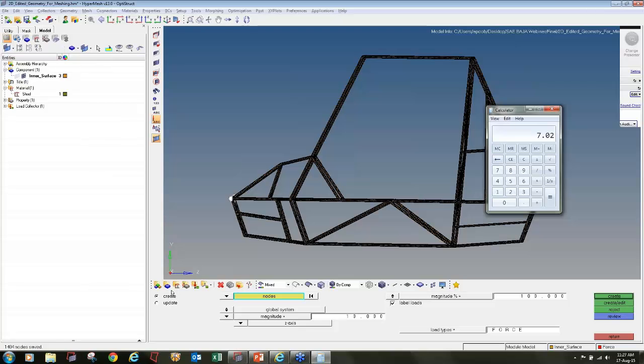That's why I initially mentioned not to apply the force which I am applying here. You have to do the calculation as per your requirement and then apply the force. Say for example, you have selected X number of nodes and you have decided to apply 4G. So 4 multiplied by the weight of the car multiplied by 10 is the total Newton of force you want to apply for front impact.